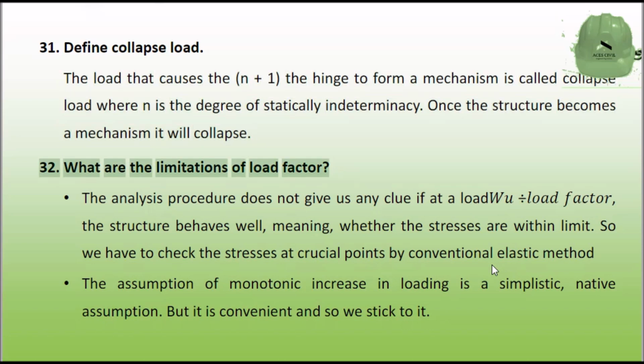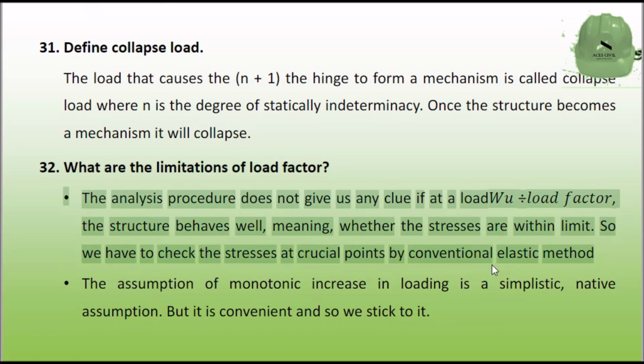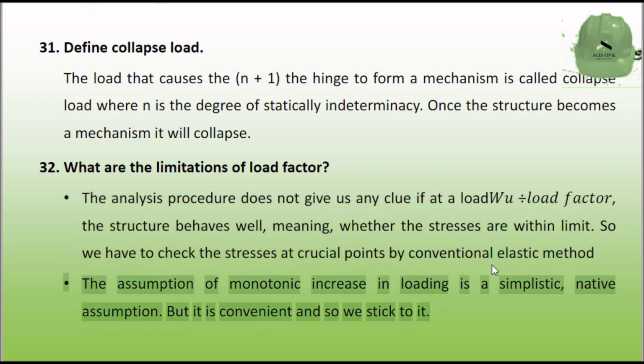What are the limitations of load factor? The analysis procedure does not give us any clue if at a load divided by the structure behaves well, meaning whether the stresses are within limit. So we have to check the stresses at crucial points by conventional elastic method. The assumption of monotonic increase in loading is a simplistic, naive assumption. But it is convenient, and so we stick to it.